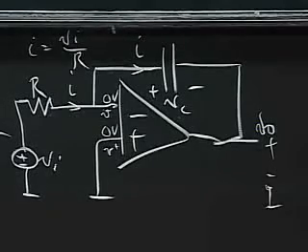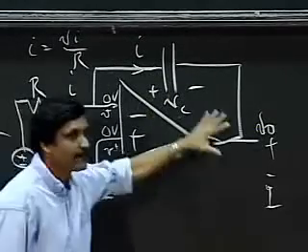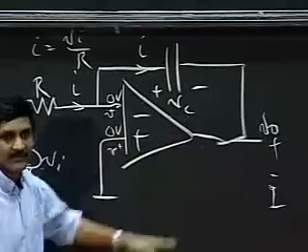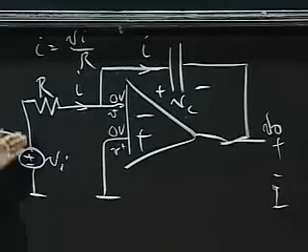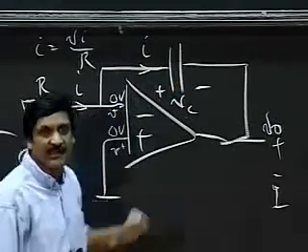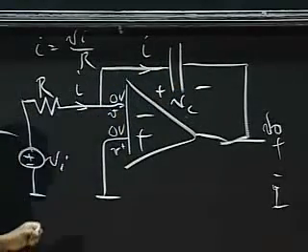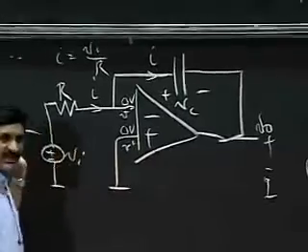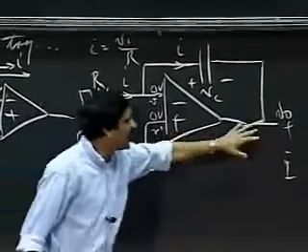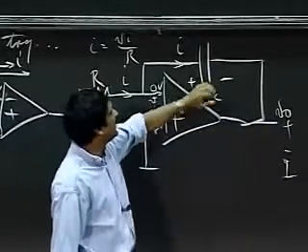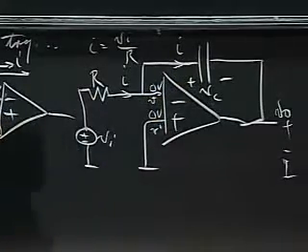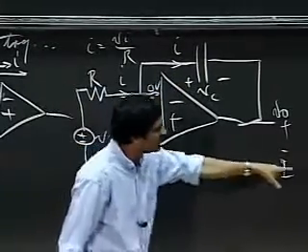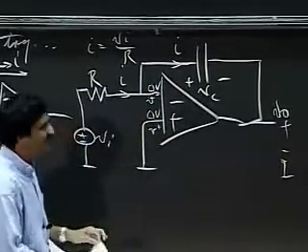So this is another very common building block. Remember this. Most of the circuits we will be seeing with op amps simply involve something here and something here. The output in this inverting connection is the input times, if it's a resistance, simply R2 divided by R1. When it's a capacitor, I get the integral form looking like this.